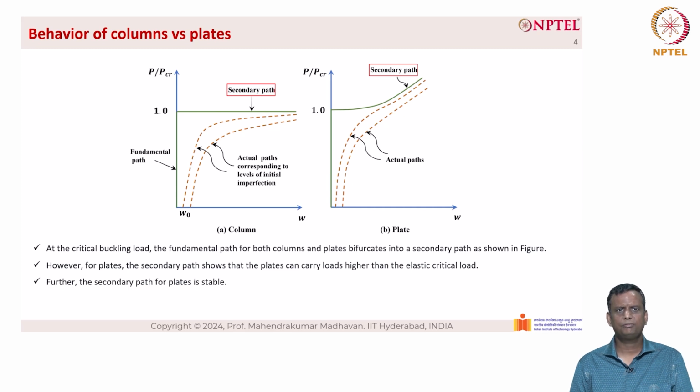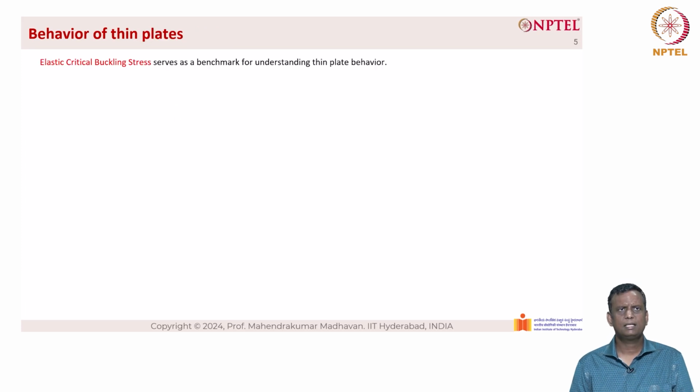Further, the secondary path for plates is stable. Therefore, the elastic buckling of a plate need not be considered as a collapse load. The elastic critical buckling stress serves as a benchmark for understanding the thin plate behavior. So you can see a timeline for the plate buckling.